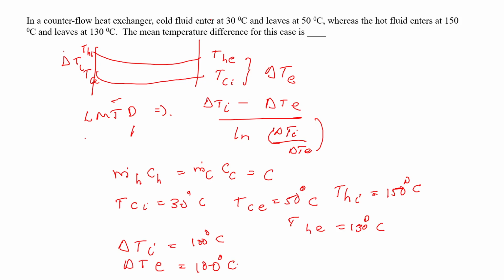But I think this pinch point depends on the minimum temperature difference, right? Yes, ma'am. That should not be negative. Obviously a negative temperature difference should not be there. And one more thing, it depends on the system also, like the temperature difference between the hot and cold fluid. It cannot be a fixed value.